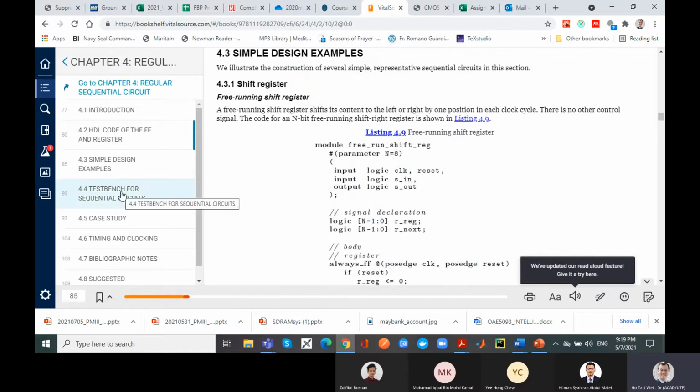And today, the lecture will be primarily SDRAM, synchronous dynamic RAM. We go through the details of the circuit and all that, because your goal is you need to develop for your assignment an interface to control that, and I want this tested on FPGA. I was thinking of getting this to merge with your lab 3, because in lab 3 you're using a RISC-V ALU and then you're writing to memory, right? ROM, RAM and all that. So now instead of just writing to plain old RAM, you'll be sending it to this SDRAM, which is a separate chip on the FPGA board. We'll talk a bit more about this tonight.